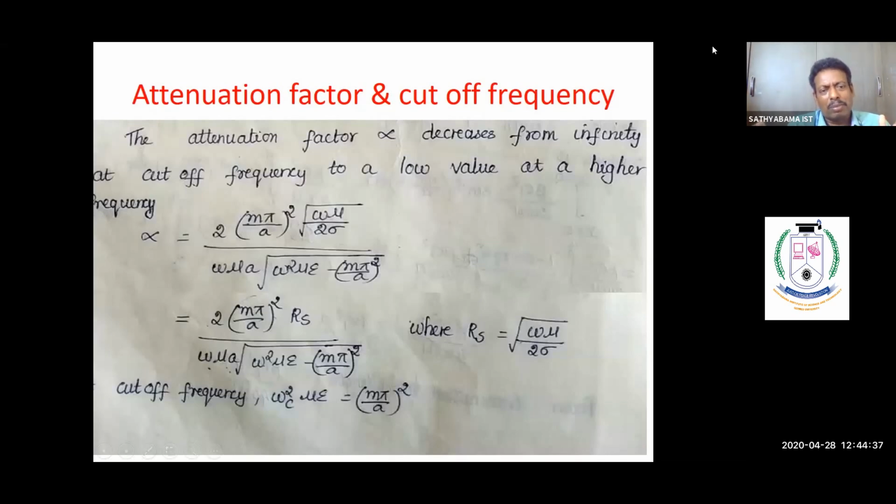That's the reason why. Waveguides are the transmission lines which have the lowest attenuation, even when compared to coaxial cable. But the problem here is we cannot use waveguides for low frequencies. Only after 3 or 4, particularly after 4 GHz, will the dimension be compact enough to practically make a waveguide. Below that frequency, it is practically not possible to make waveguides and we cannot use them. So this is a unique drawback of the waveguide: they can conduct power only after a certain cutoff frequency.